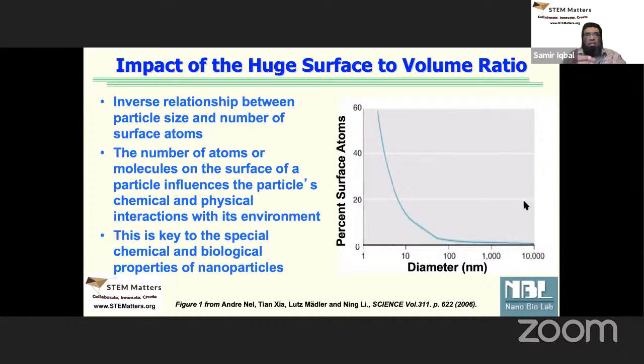Now a resistor is a two-terminal device. You have a region, you put two connections to it, and you know what the resistance is. But a transistor is a three-terminal device. You have interesting things happening where you have source and drain, and then you have a gate area. You have to control the gate. How close you bring source and drain, how thin you make the gate dielectric, that is the difficult part. So making resistances and capacitances is slightly easier than focusing on transistors.